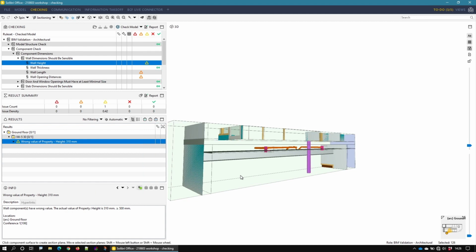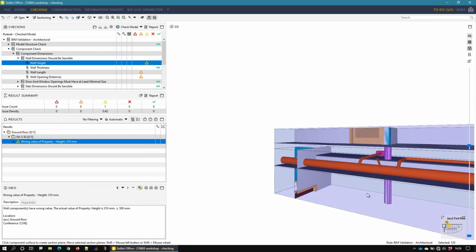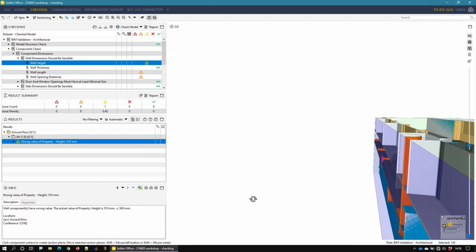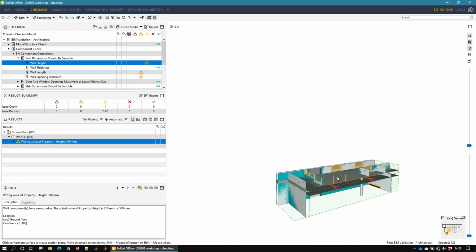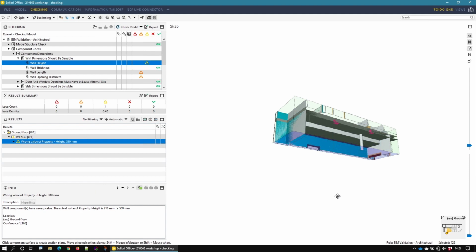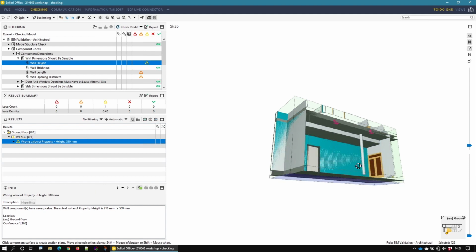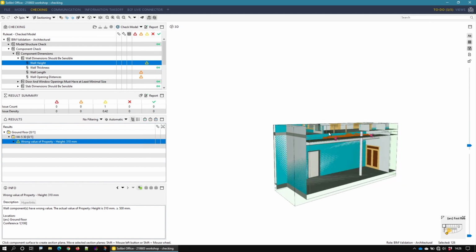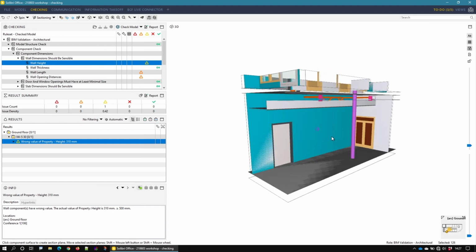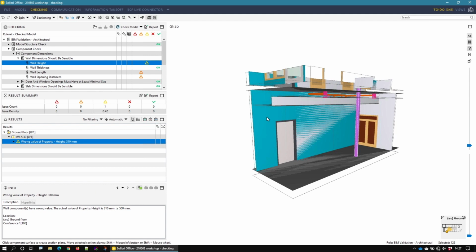So with that in place, what I can then do is actually just move some of these planes. So there I've got the wall behind what I was looking at. And if we go underneath, we can take this bottom one and extend this downwards and we can see into the room, we can see the thing we're looking at. If we cut this backwards, I'm going to press T to turn off the sections, and then we can present this quite nicely in the middle of the screen.